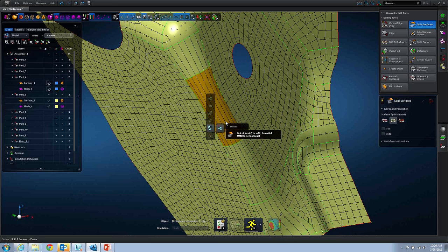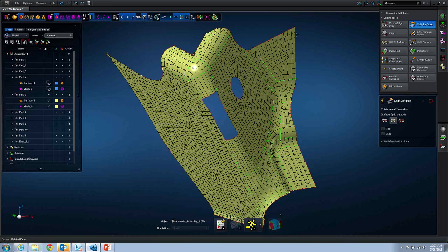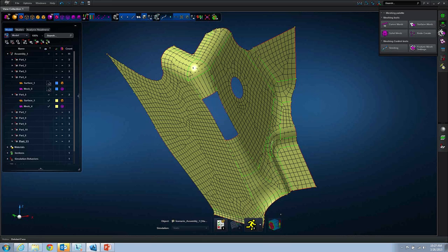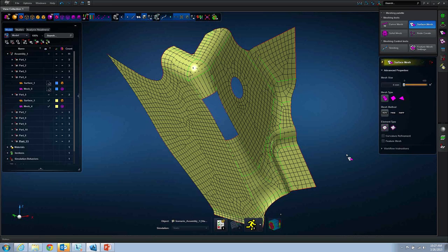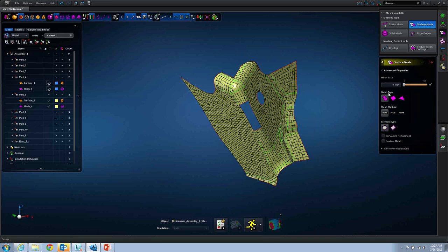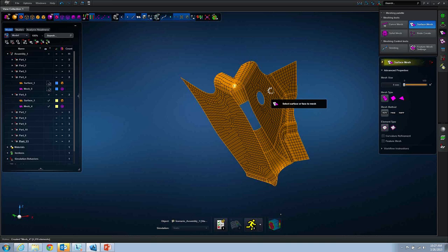And basically, I'm making a part a little flexible and creating that hole. Let's assume that along the edge, it is glued to the other parts, and just for the sake of showing the generative behavior and where the glue should be getting automatically updated, I'm going to remesh this part maybe from 4 mm to 5 mm and change that mesh.